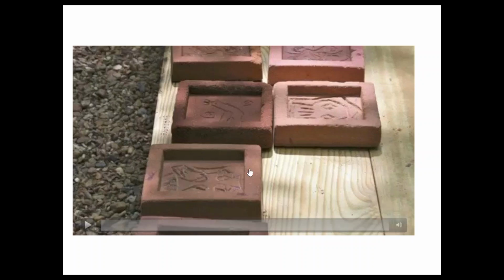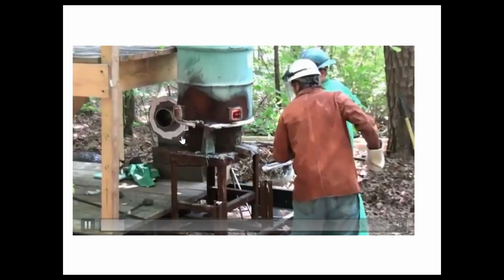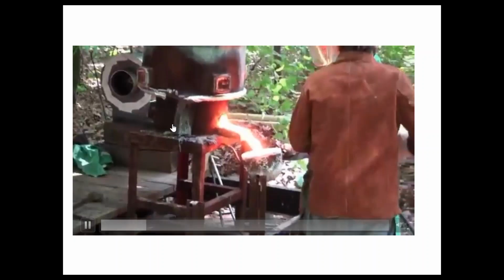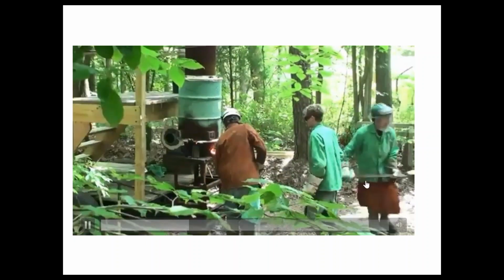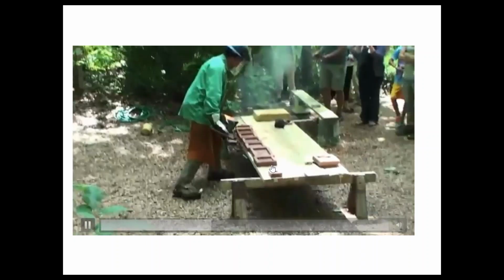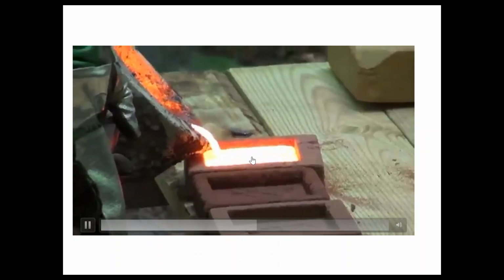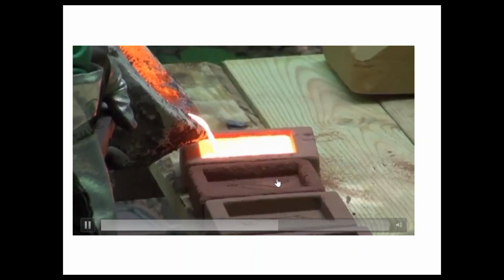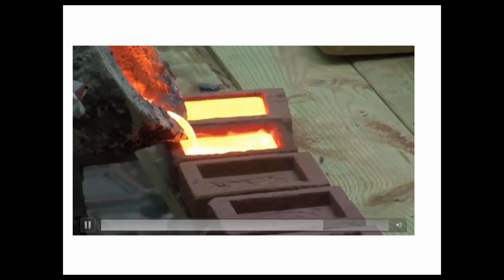So these are molds, and when we cast, we pour liquid metal into molds. These are molds made by students who scratched some image in it, and they're used to make plaques. And you can see in this video, they're actually tapping. There's where the air goes into the furnace. They're tapping cast iron into a small ladle, and when they pour that small ladle into these molds, then when that cast iron freezes, it has the shape, so each kid that made a mold will get his little plaque with the image that he scratched in the mold.